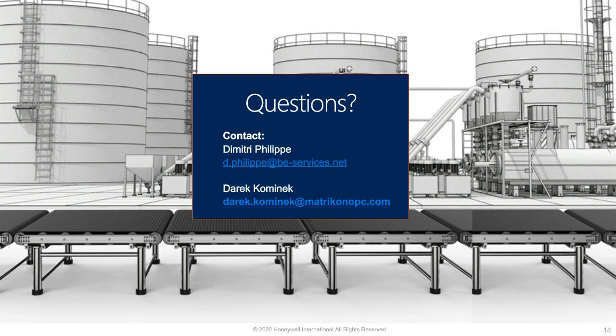It does definitely depend on the CPU that is on the device, but we have experience with that number of tags on a not so strong CPU, on a PowerPC, in a process automation application, oil and gas, and the performance is quite okay, especially if we talk about CODESYS. Other systems have the same possibility to set task priorities, so you can set a higher priority for the control task and a lower priority for the OPC UA communication.